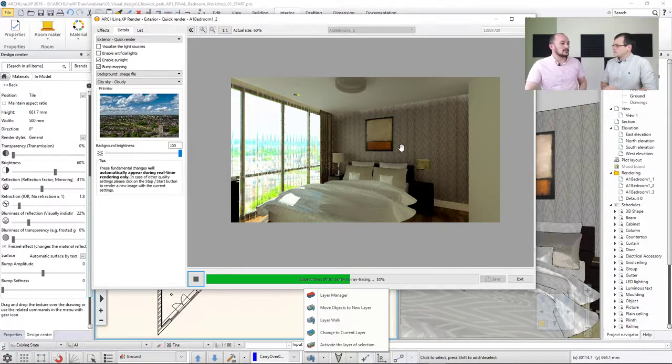And this actually leads to the third factor of rendering time, and that's the number of surfaces. The more surfaces, the more objects you have in your model, rendering will also take longer. So in this case, just as we did already with this model, we filtered out everything else, because now we are focusing on this single room. So we turned off all the layers that host the other parts of the rooms and sanitary ware and everything else. Now we only represent items in the 3D with the 3D hammer that affect our current visuals at this very moment.